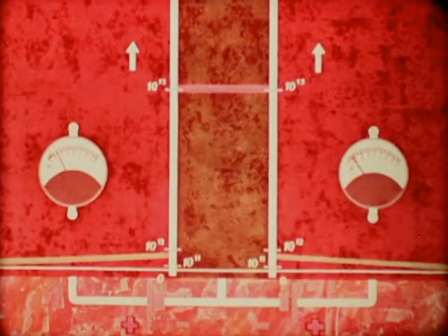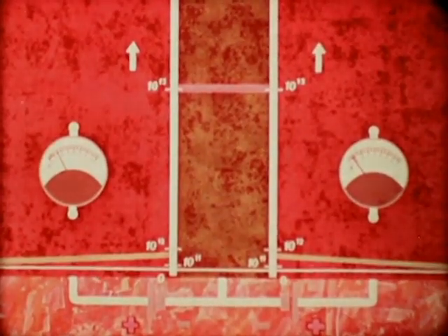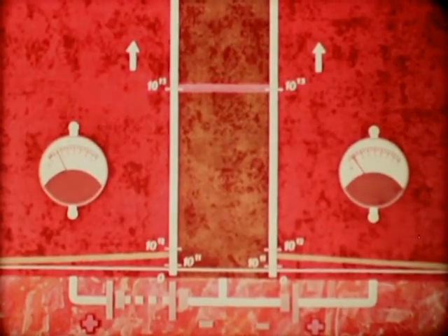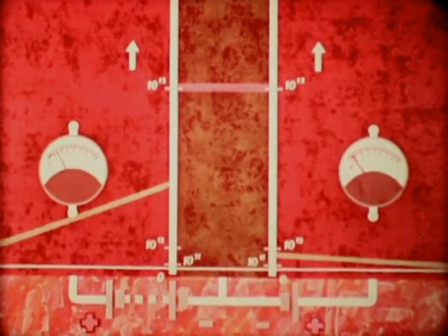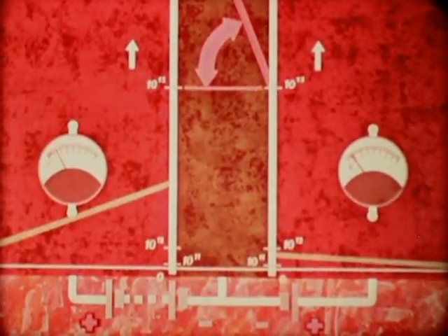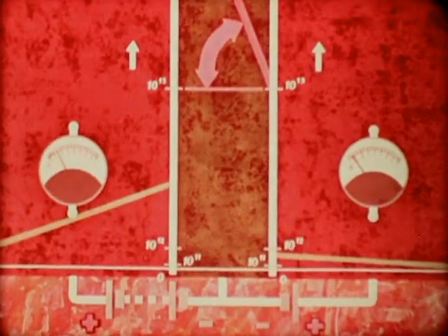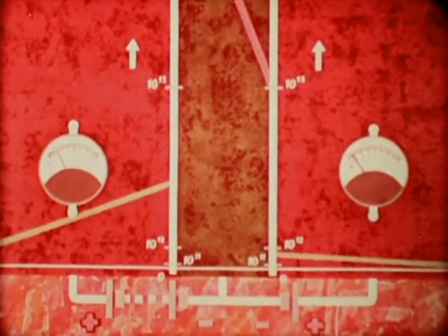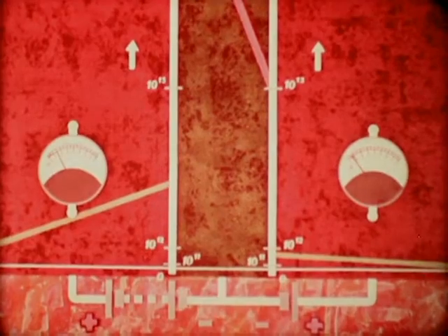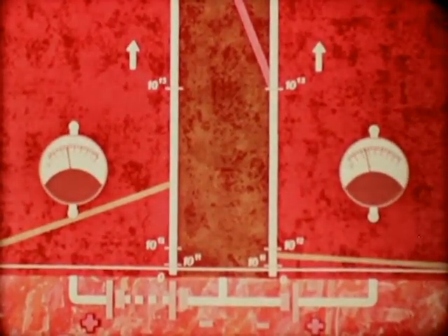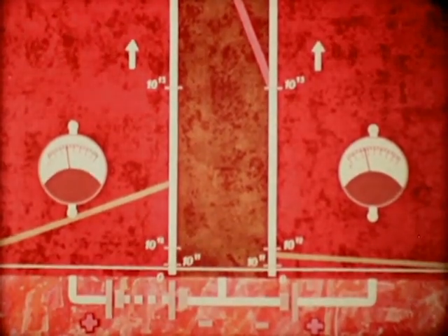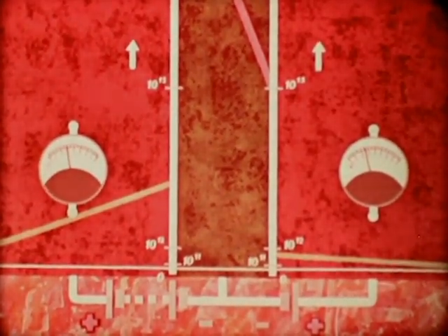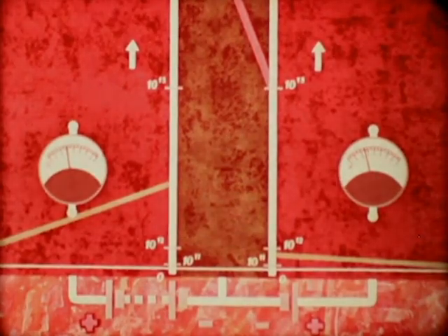But if we now increase the value of the forward voltage applied to the emitter-base junction, the number of holes diffusing from the emitter into the base will increase considerably, and most of these holes will be absorbed by the collector. The large angle now formed by the concentration graph of the holes in the base indicates that the emitter and collector currents flowing are also large. However, the collector current is now flowing in the opposite direction.